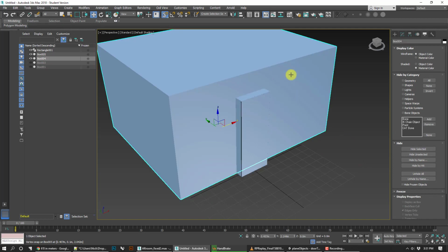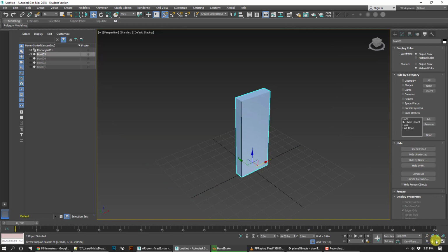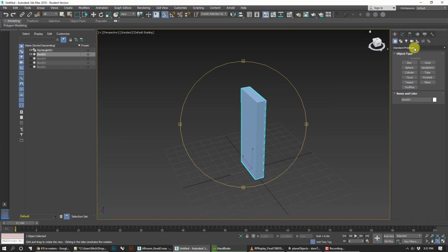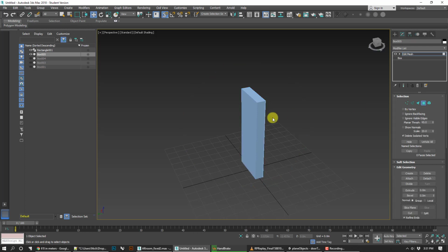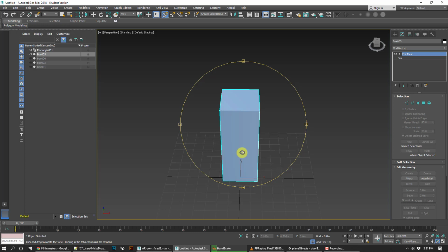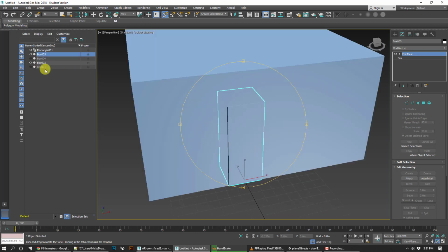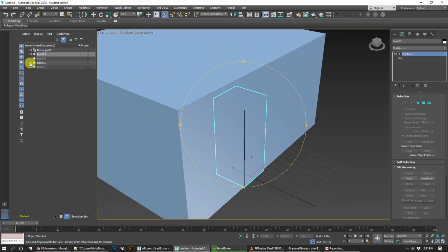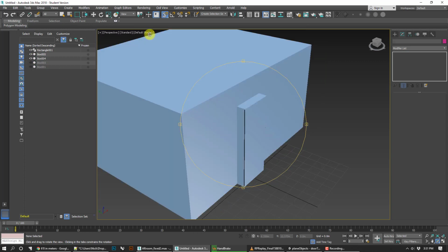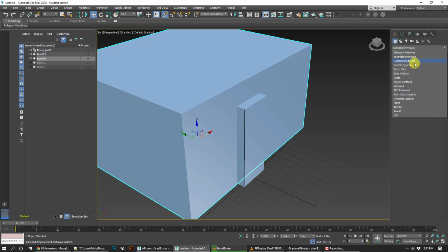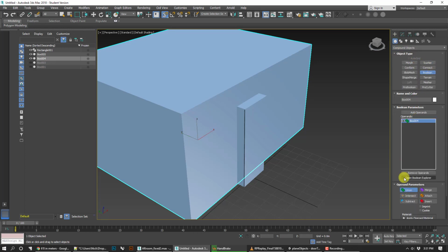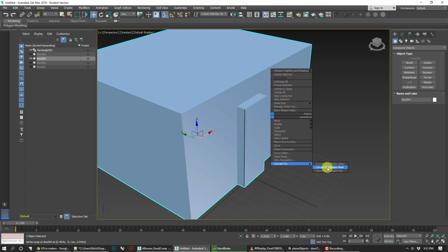Okay. And I'm gonna do this, and we go back to this box here. That's embarrassing. Okay, and then throw on an edit mesh. Go here, and then just make sure that that is fully inside that room before I boolean it. No, that's the outside box. I don't want that. I want this one. Okay. Let's go back to create objects, compound objects, boolean, union, add operand. Okay, and then let's go ahead and collapse that.